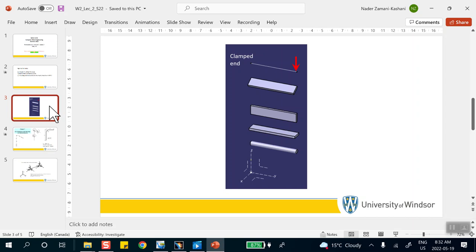It makes no difference. This is why when you do beam problems, the easiest case is a circular cross-section, because you don't have to worry about its orientation. But if it's anything but a circle, you have to tell the software that there is a point which determines the orientation, and we'll get to that in a second.